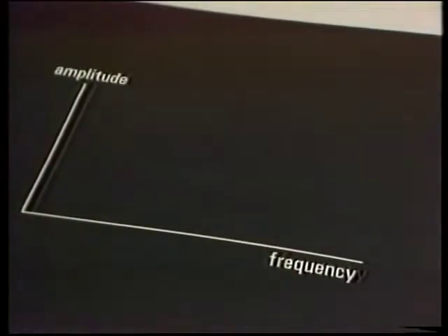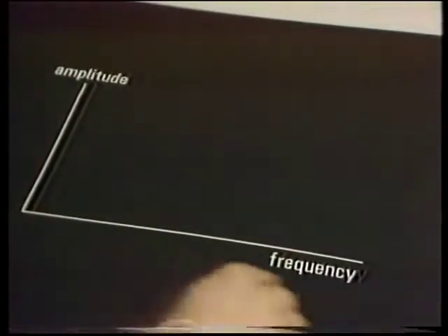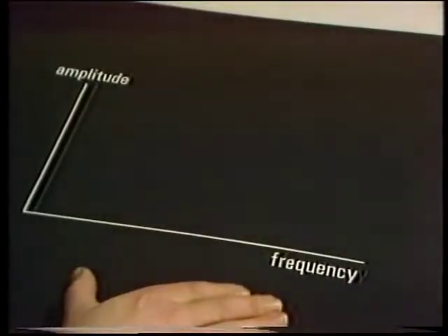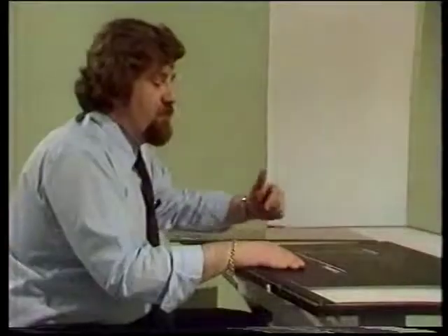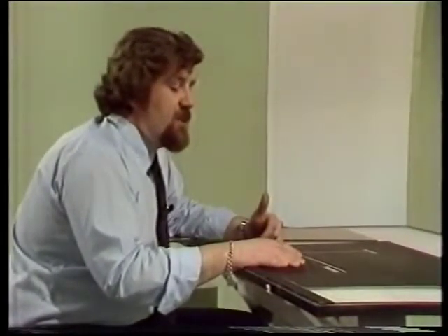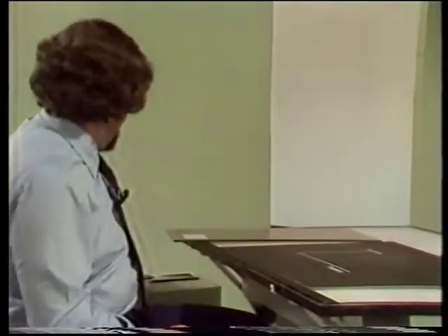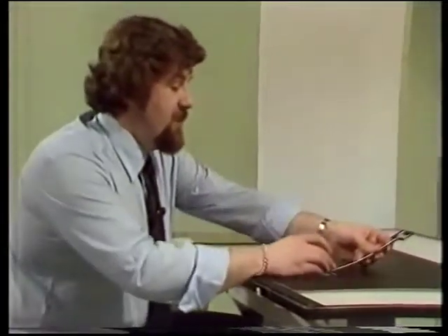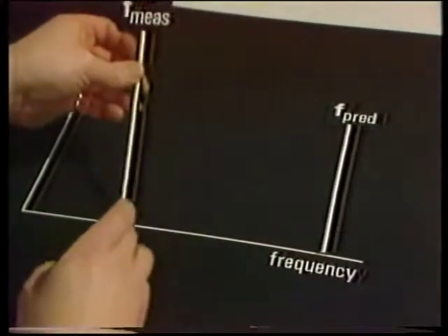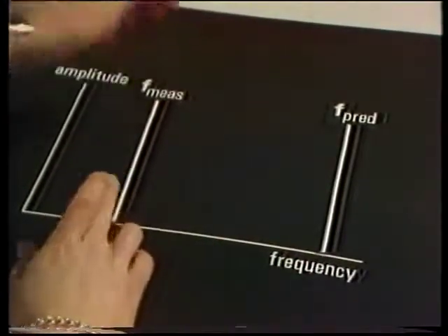Here we have amplitude plotted vertically and frequency horizontally. And this is a linear frequency plot, not the usual log type. Now, what we observed was that at high frequencies, the oscilloscope indicated a low frequency. Now, I made some measurements earlier in the day, and what I found was that the generator, reading about 4 kilohertz, produced a measurement on the oscilloscope of about 1 kilohertz.